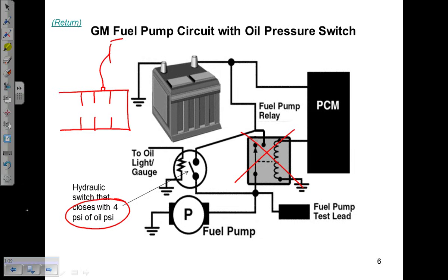We're putting a pressurized container mixed solution of gasoline and some kind of cleaner when we're doing the injectors. And when you do a procedure like this, you have to make sure that this rail holds pressure on shutdown. Okay? For example, let's say here's our fuel lines. They run back to the tank, say a return type system, and you put a gauge on this, and your gauge is dropping when you shut the key off.